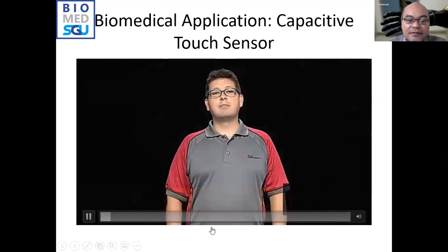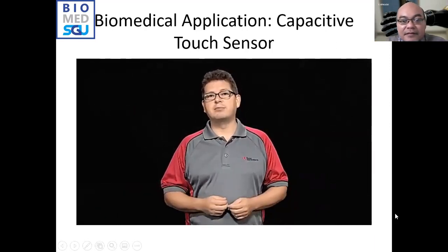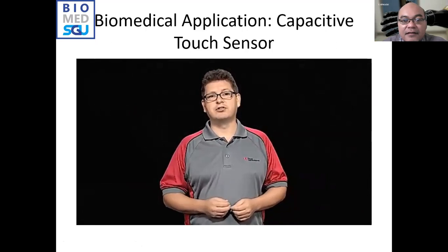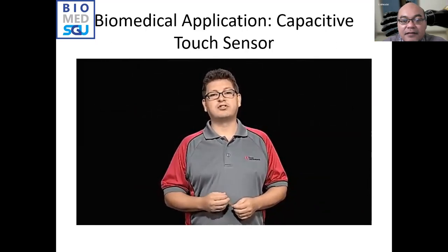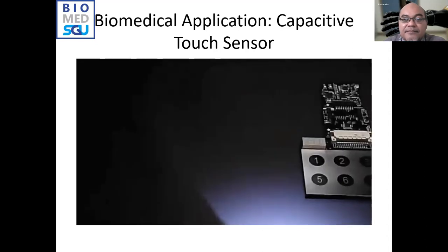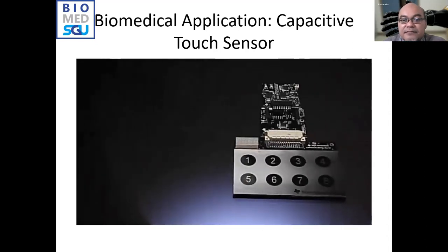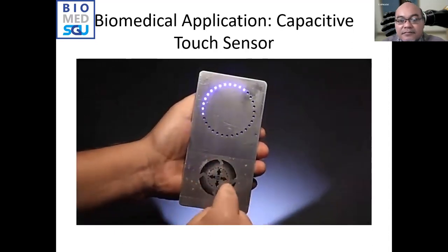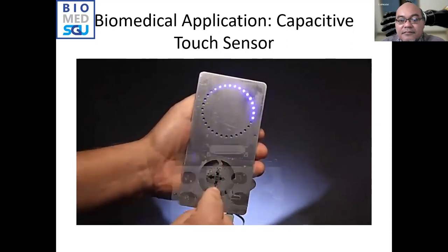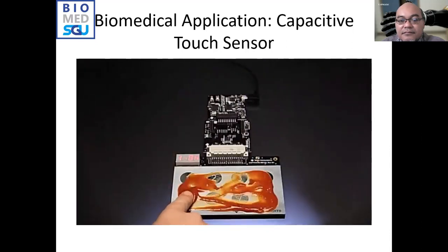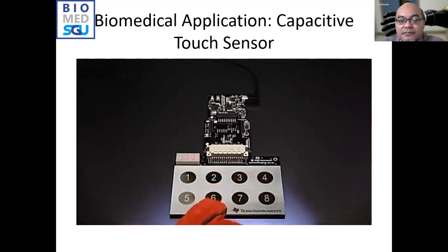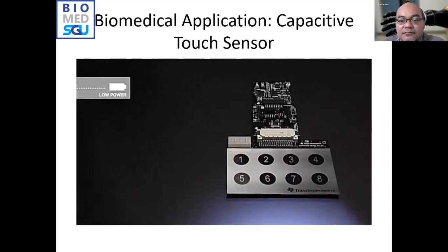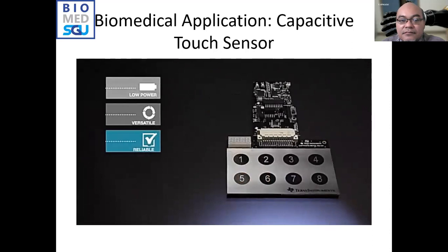Mechanical buttons fail frequently in wet, dirty, dusty, grimy environments such as factory floors and cooking ranges, as well as with outdoor applications such as electronic locks and elevator panels. MSP430 MCUs with Captivate technology can be used to implement metal touch solutions, allowing highly reliable and elegant buttons, sliders, and wheels. Touch-through metal is inherently waterproof, dirt-proof, and operates while wearing gloves. Captivate technology offers the industry's lowest power, versatile, noise-immune capacitive touch solution with an ecosystem that can have you designing your system in less than 5 minutes.